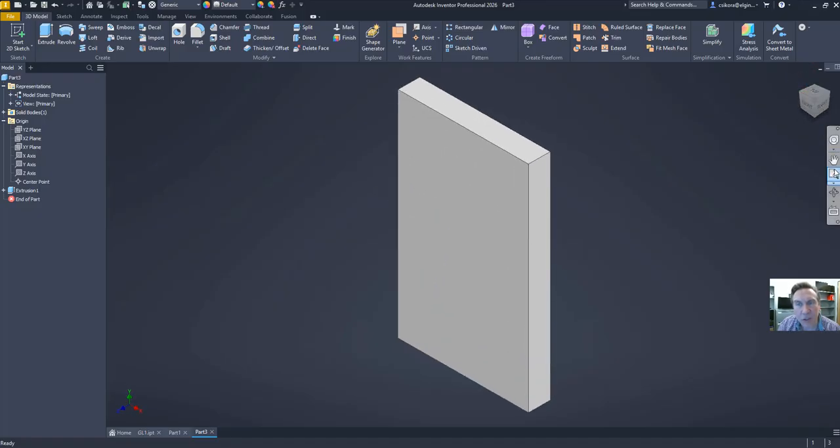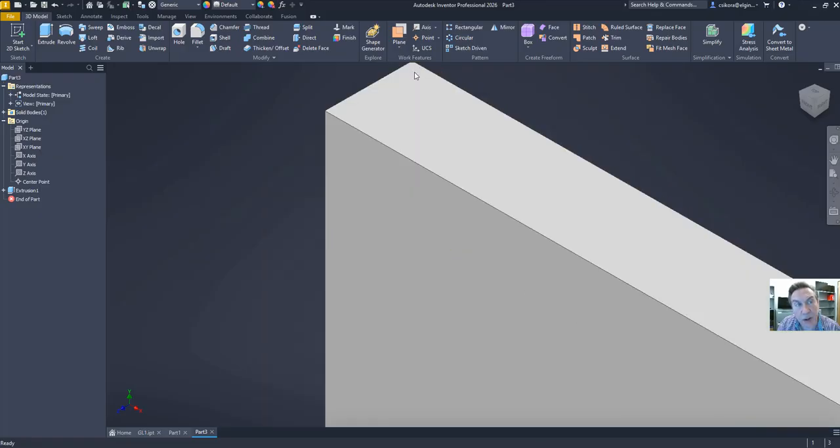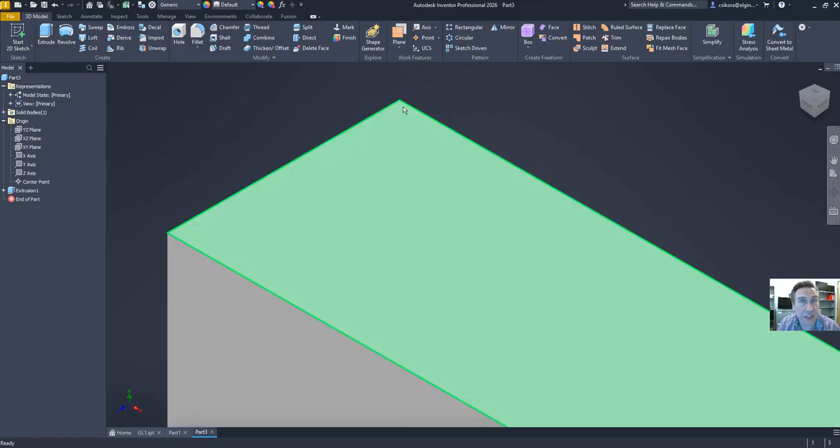There are these buttons too that enable you to zoom to fit, to orbit or rotate, whatever you want to call it, and things like that. So feel free to tinker with these as you go along. But now that you've seen how to rotate that way, here's probably my favorite way to rotate. On your mouse, you usually have a wheel. Now, if you use the wheel, let's say we want to focus this upper corner. Get your pointer over it and then scroll the wheel towards you and keep the pointer focused there, and you'll see it will continue to zoom up where you're pointing.